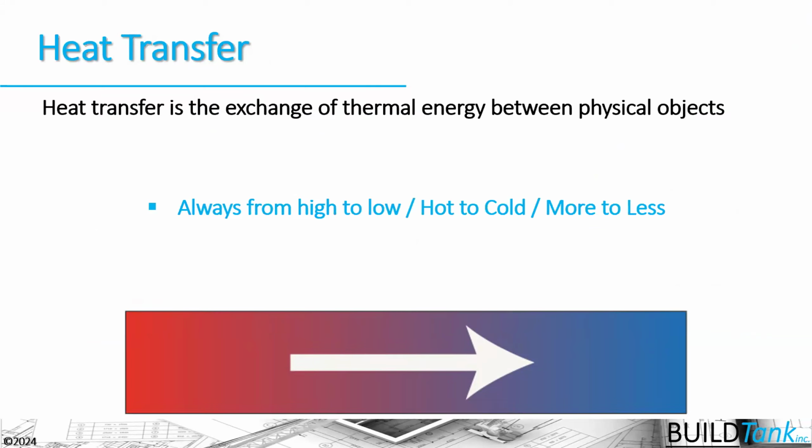So when we have clearly defined our building thermal envelope, we've also created what we call a delta T location in our heating seasons and our cooling seasons so that we know which direction the energy is moving. Is it moving from inside the house to outside the house in the wintertime, or outside the house to inside the house in the summertime?